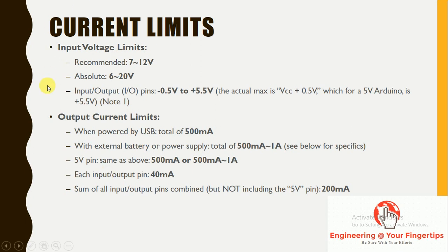So you have to make sure somehow that it is only driven with 20 milliamps. Putting an appropriate resistor in series with the LED, using Ohm's law, V equals IR, you can choose the right size resistor to make sure the current never exceeds a certain threshold.